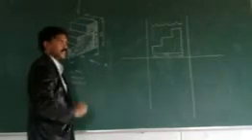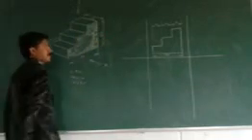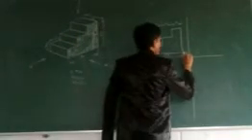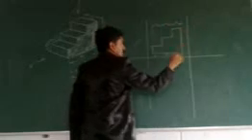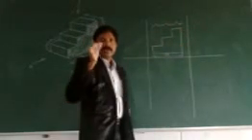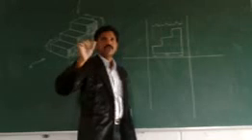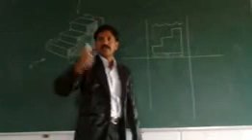Coming to the height, the total height is 45 and the splits are 15, 15, 15. See how I am going to maintain the chalk field. These are the actual lines, that is nothing but the object line. For the object line, use the H pencil, and for the projection line, use the 2H pencil.